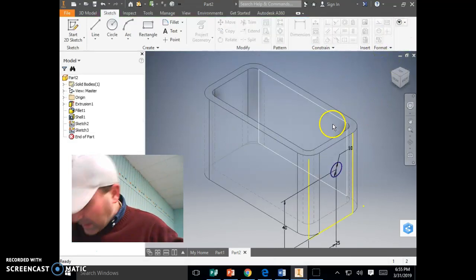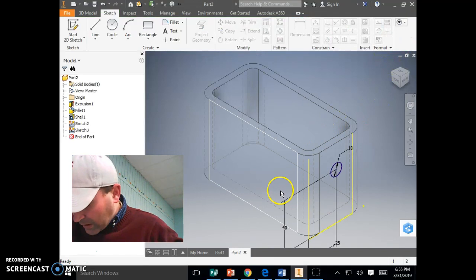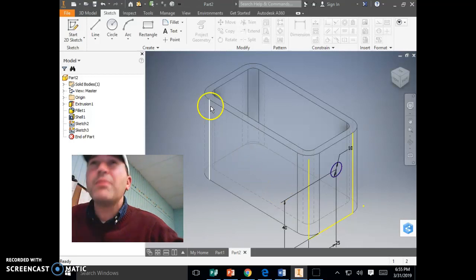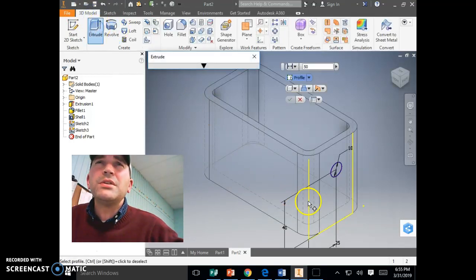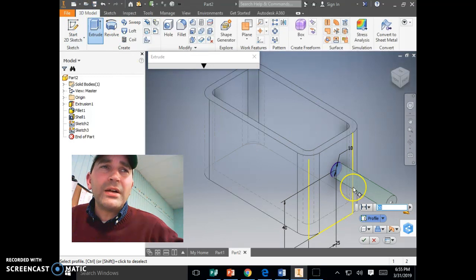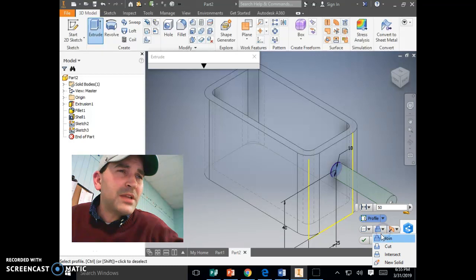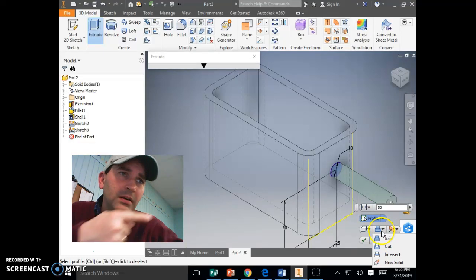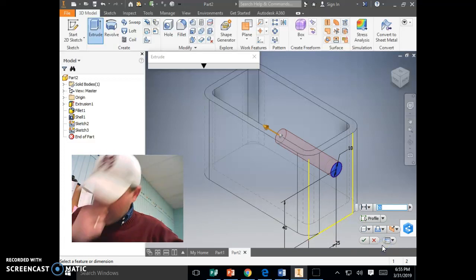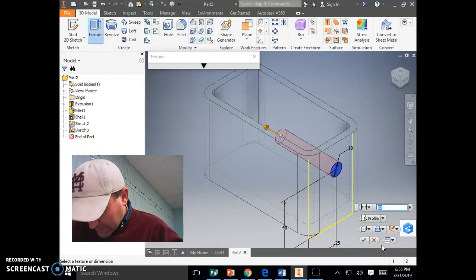And there it is. And now we're going to cut the hole, extrude the tool using the extrude tool. All right, so choose the extrude tool on the ribbon bar. So 3D model, extrude, and we're going to extrude that circle there, but we're cutting a hole. So we're going to go to the second button and cut. Look over there where my mouse is, click the second button, go down to join and cut. Click cut.